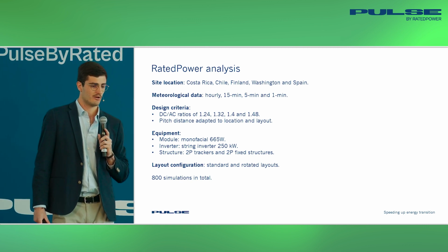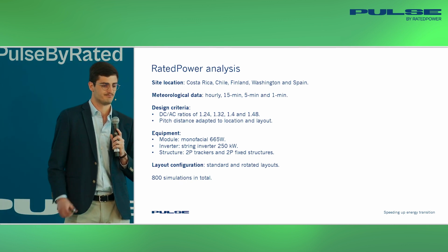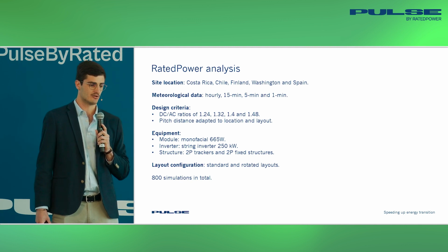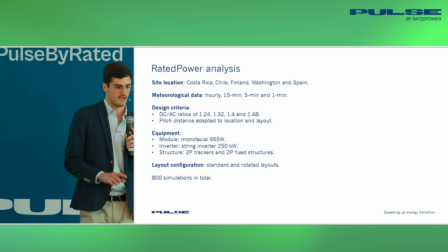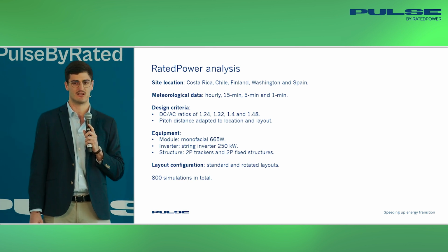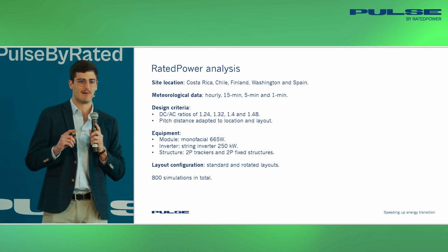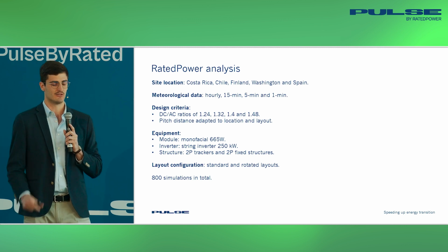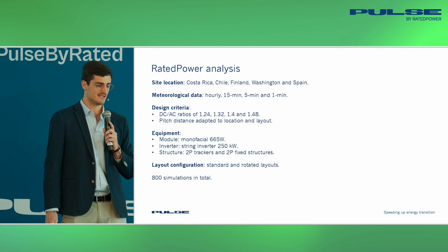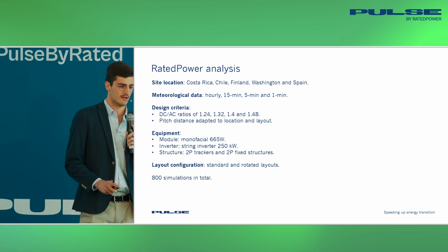In terms of equipment, we used a monofacial module, a string inverter, and also tested both trackers and fixed structures. Apart from that, we also evaluated standard layouts, north-south and east-west oriented, but also rotated layouts, evaluating different angles of rotation of these layouts. This means that we evaluated 800 simulations in total, and now we will see what were the results that we observed.